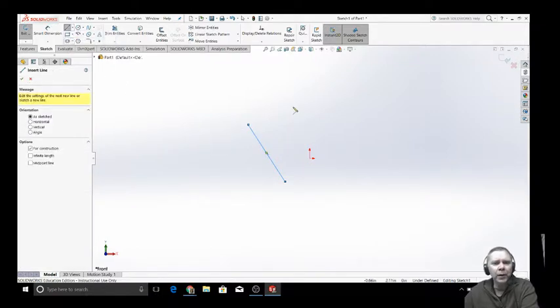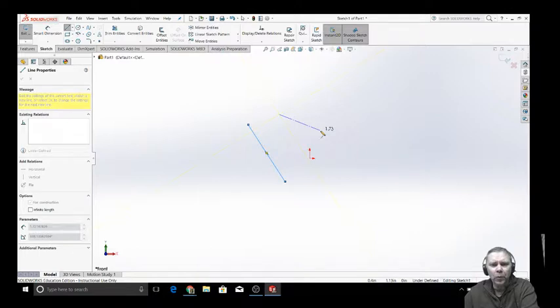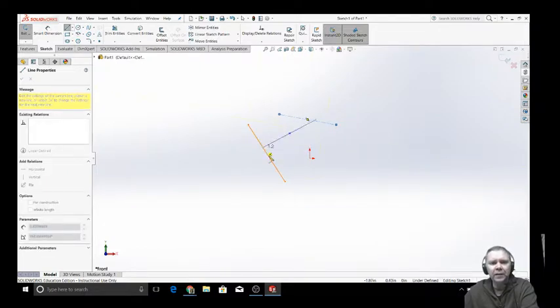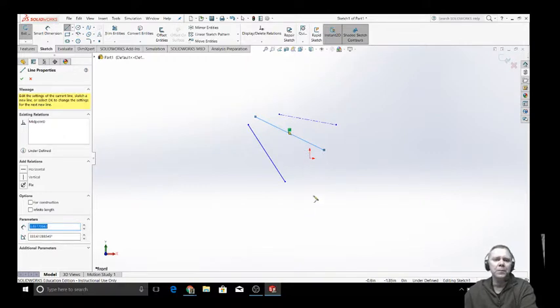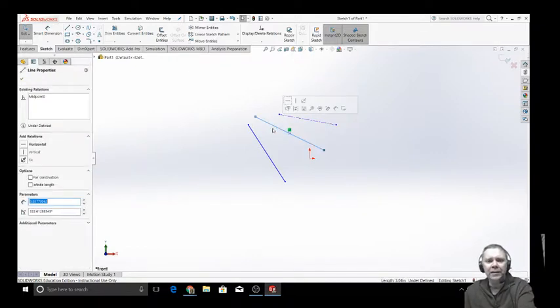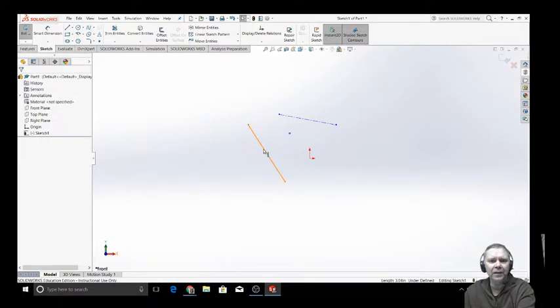You can draw a center point line. Center point lines aren't actually part of the drawing, but are used for reference or things like that. And notice when I get close to vertical, it seems to snap to vertical and snap to horizontal to help you out as well. There's the center point line, and then there's the midpoint line. The midpoint line starts in the middle, and as you drag the line out and rotate it, it continues out from there. Okay. Now I can escape out of this, and I get my pointer back. Now if I select any of these lines, that's the active line. I can delete it, and I can delete that line, and I can delete that line.